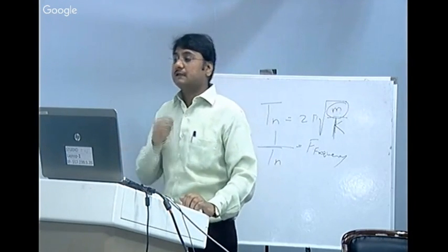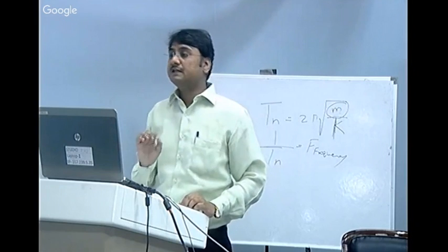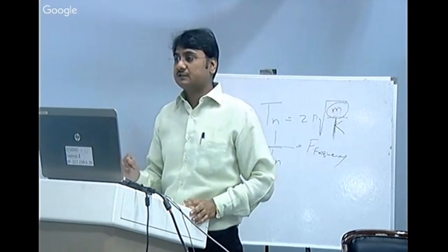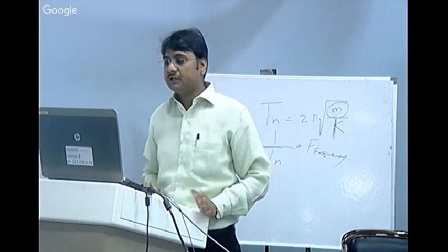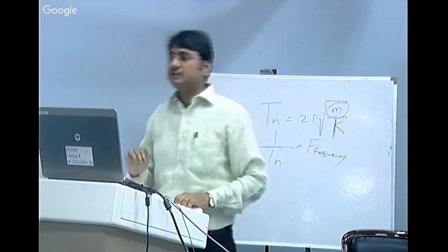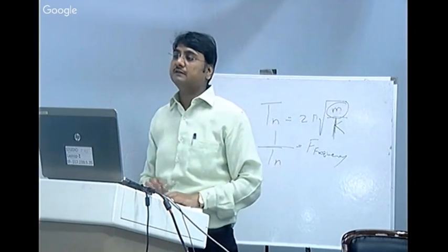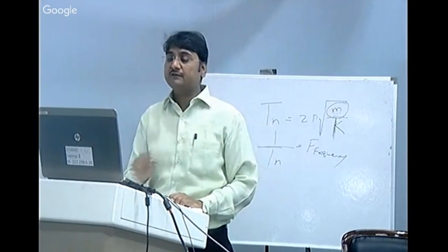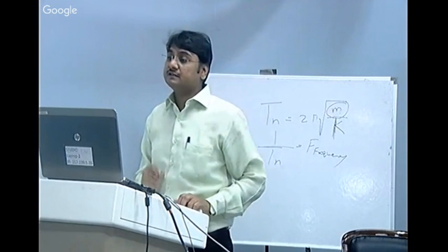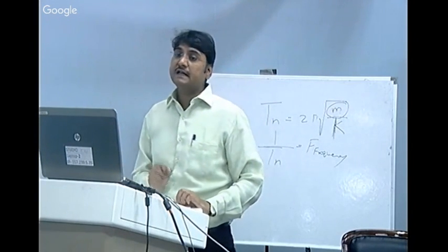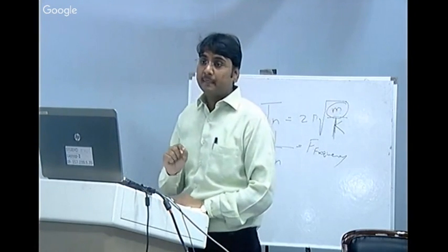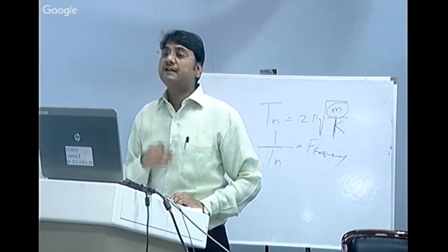Why? Because at that frequency, the structure resists the oscillations very little. It happens during an earthquake also. In case of single story buildings, this fundamental frequency is high. That means if the earthquake is a long period earthquake, then it damages single story buildings more as compared to 2-story or higher story buildings.